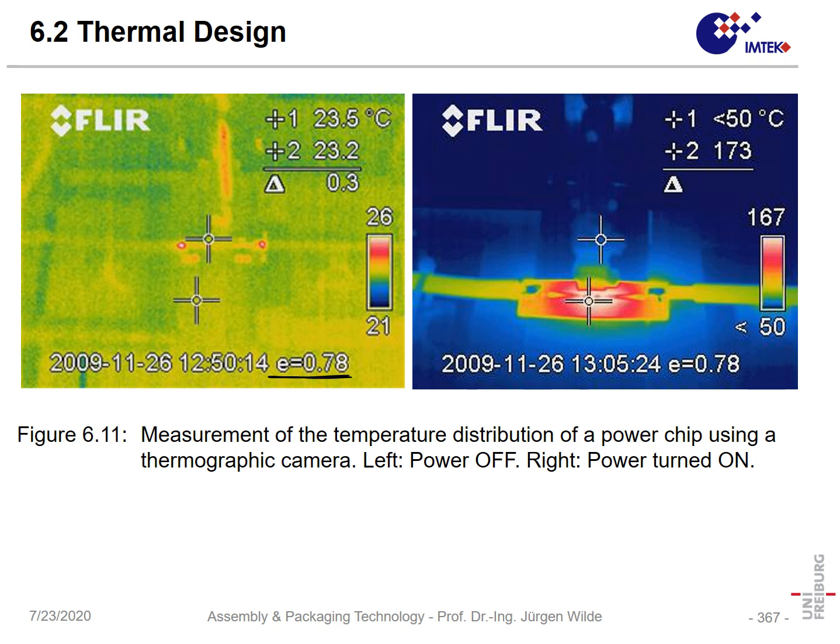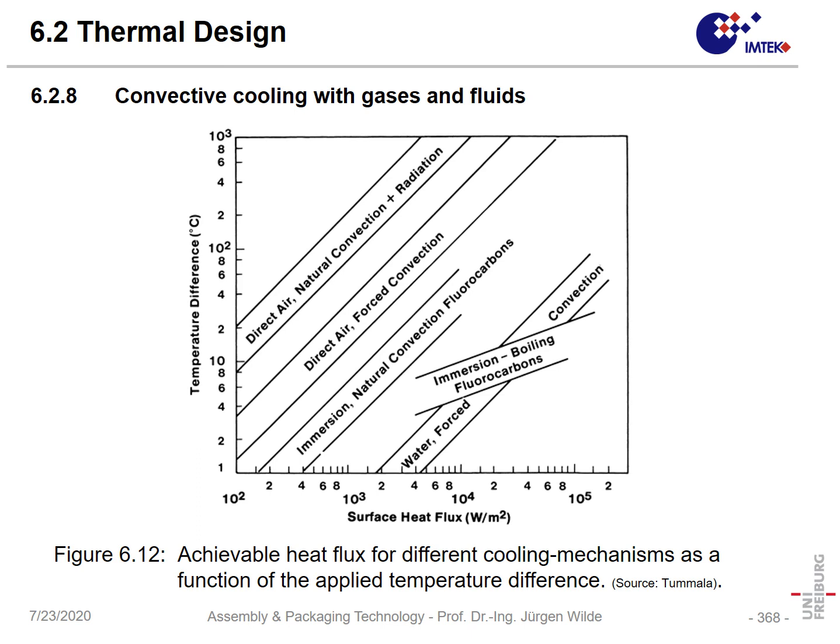So for instance, you must make, at least at one point, an independent measurement, and you must calibrate the surface on which you want to make the temperature measurement. And that's the reason why emission of infrared radiation is very important in electronics, not for cooling, but for contact-free measurement of temperature distributions in assemblies.